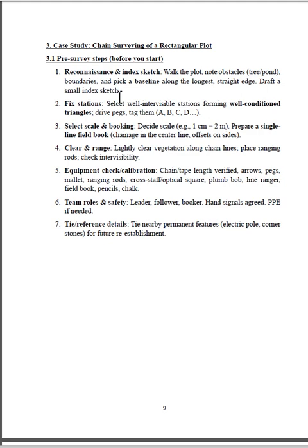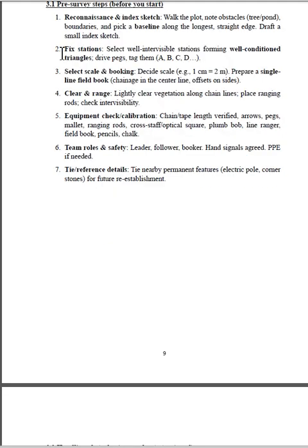Draft a small sketch. Second point, fix stations. Select well intervisible stations forming well conditioned triangles. Drive pegs, tag them A, B, C, D, etc.